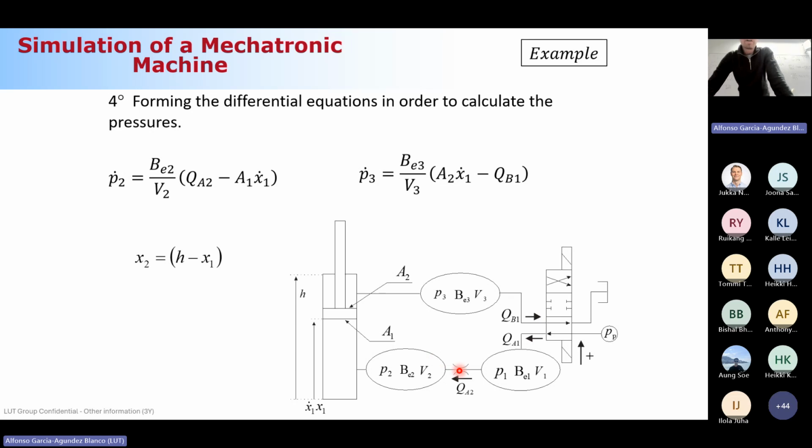And now, do I have an outcoming flow rate in control volume 2? Is there a line? No, exactly. There is not a line or a pipe that is putting out a volumetric flow rate. So in the previous differential equation, you would have QI incoming, QO outcoming, which you don't have here. And the final term, if you remember, was the time derivative of the volume, because of the piston motion.